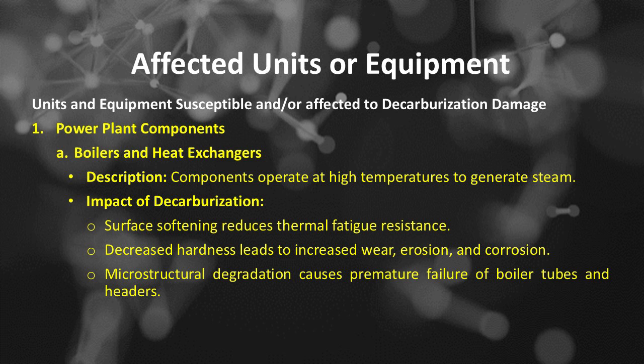Number A, boilers and heat exchangers. Description: components operate at high temperatures to generate steam. Impact of decarburization: surface softening reduces thermal fatigue resistance. Decreased hardness leads to increased wear, erosion, and corrosion. Microstructural degradation causes premature failure of boiler tubes and headers.